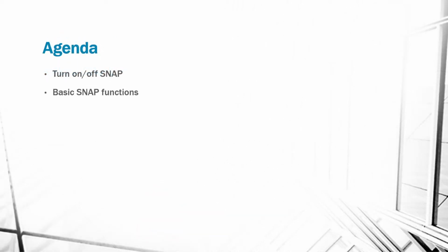Looking at our agenda, what we're going to be doing is looking at how to turn on and off the snap functions and some of the basic snap functions, such as our midpoint, our endpoint, our tangent, and our intersection snap functions. So I'll meet you over in AutoCAD.